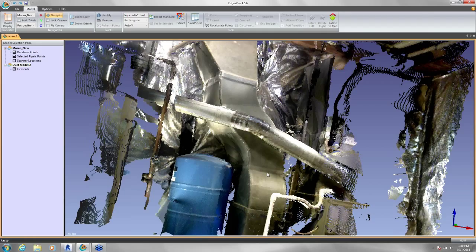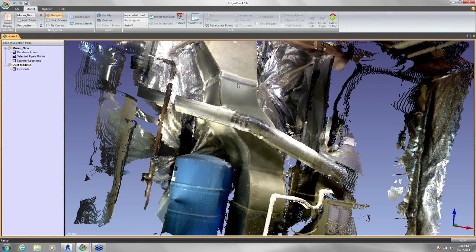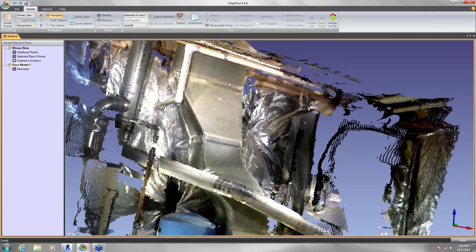Then we've got a combination elbow/transition tool that adds them in combination with each other. So I'm going to skip over this transition and an elbow, and I'm going to model this straight section that forms the boundary between these two elbows in this S. And then I've got another elbow and a transition, and I'll model another piece of straight section here at the top of this transition.